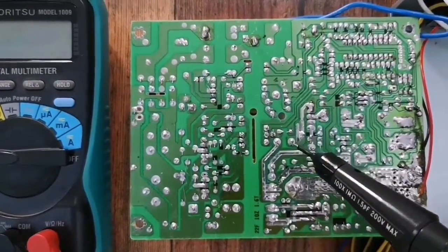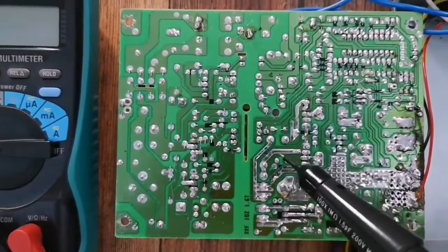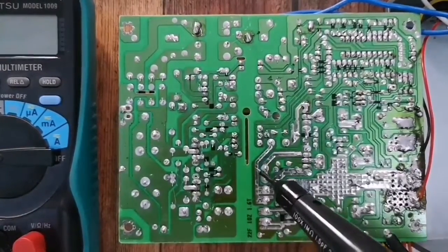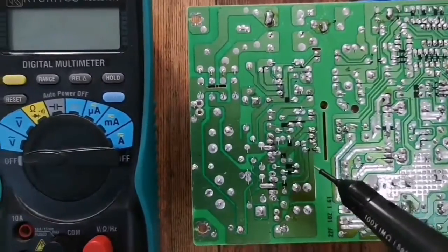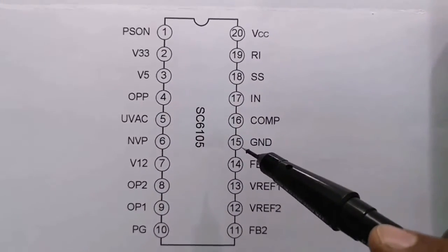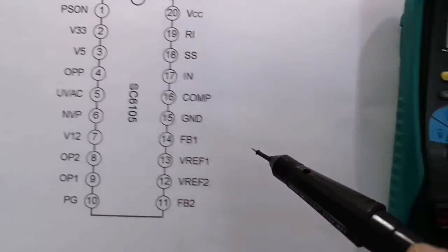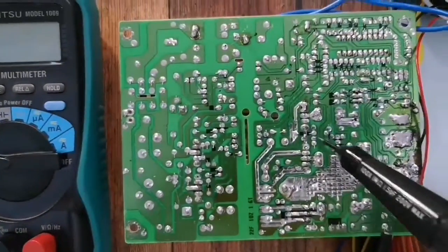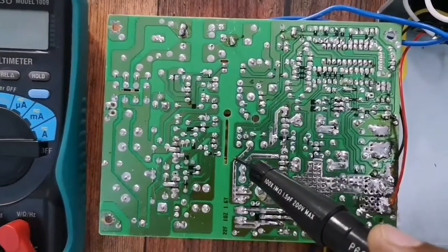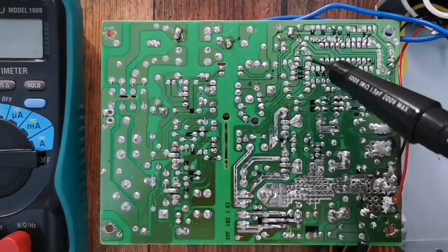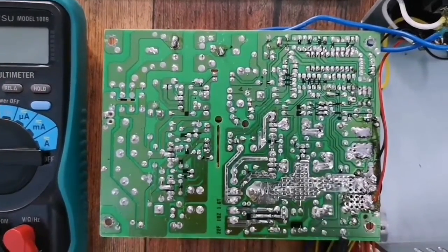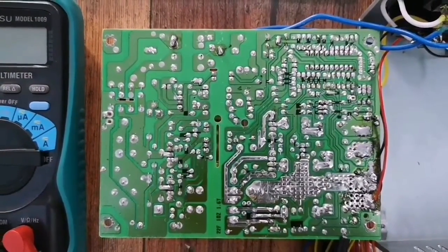One important tip here. Yes, we might not be having the schematic diagram for the board, but still we can use the datasheet and pinout of the IC as a helpful tool. Another tip, this type of board is a single layer PCB, so it is very easy to trace the circuit from one side compared to multi-layer boards where it is very difficult to do that.